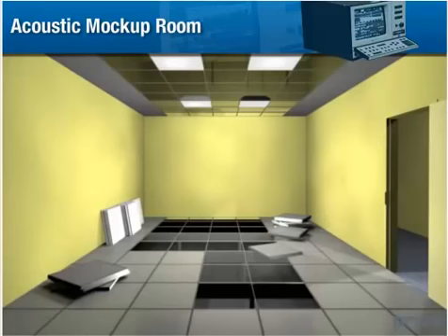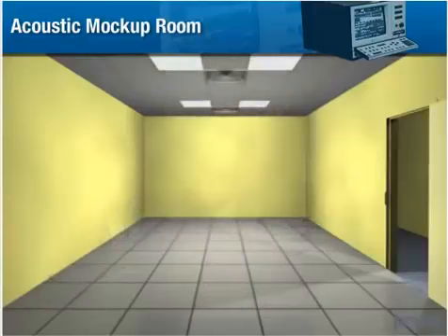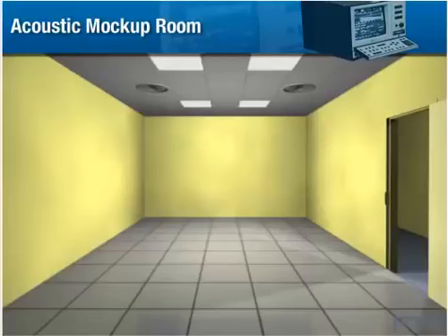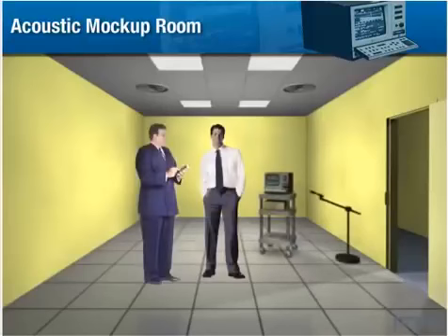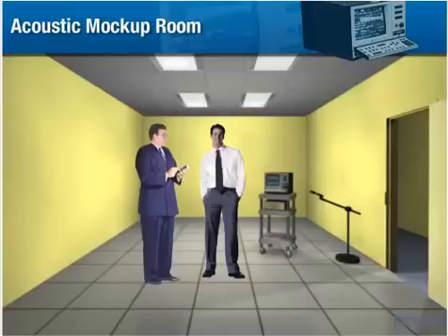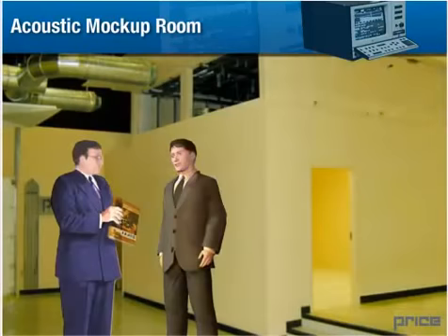Mock-ups can be developed for each project's unique specifications, including terminal unit type, size, air volume, ceiling construction, etc. Acoustic mock-up tests are a very effective method of verifying room NC levels as opposed to relying on the theoretical calculations for terminal unit applications. Visitors can listen to the system in operation as well as be provided with sound measurements.